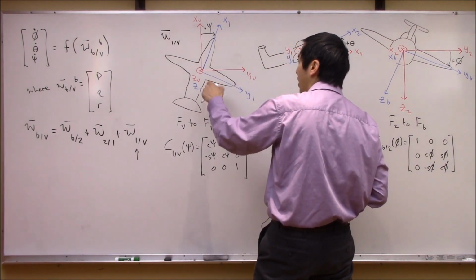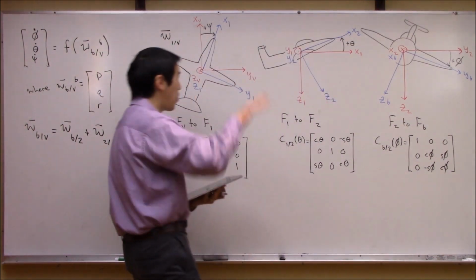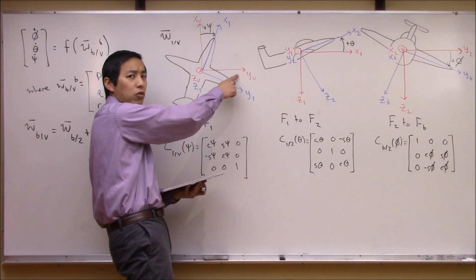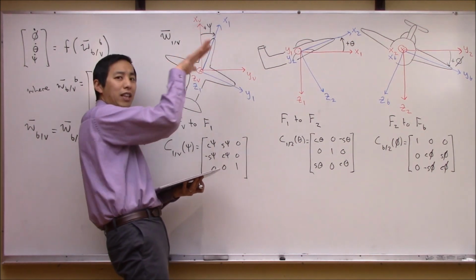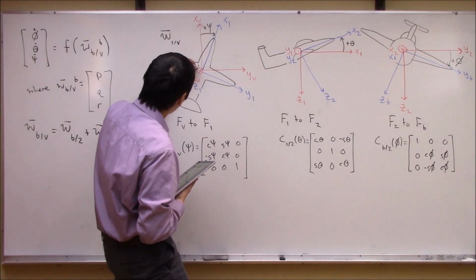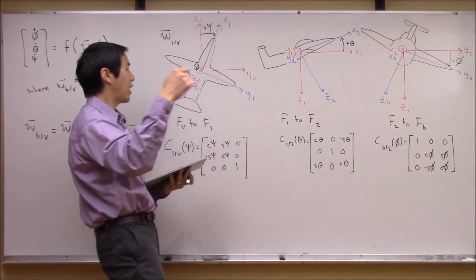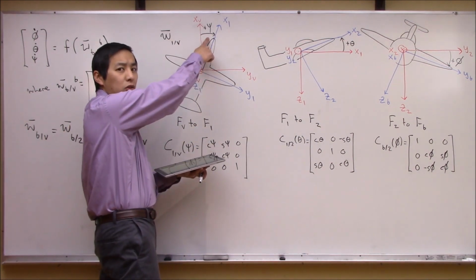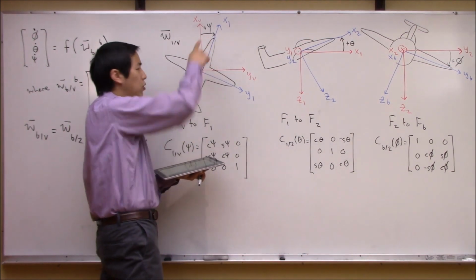As a vector, where do I draw that? Well, you see that they share a z-axis, right? And that is in fact the angular velocity vector of how the blue frame is rotating with respect to the red frame. It's directly into the board. So if I were to draw this in black, I would draw it right over this here. It would be a vector going into the board, and its length would be the magnitude of psi dot. It would say how fast those 2 frames are rotating.